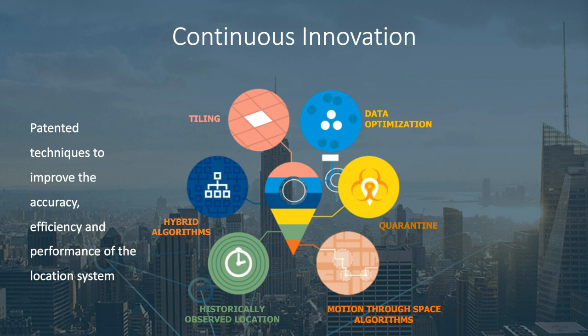Yeah, like exactly. But you're right. You're talking about Sigfox just as an example where 12 bytes of data can be transmitted in each uplink from a device in sort of a 26-byte frame, which includes the overhead, and talking about 140 messages per day, which is what do you want to send, when do you want to send it, how much of that do you want to send for what you're trying to do or perform as a function. You're right about that.